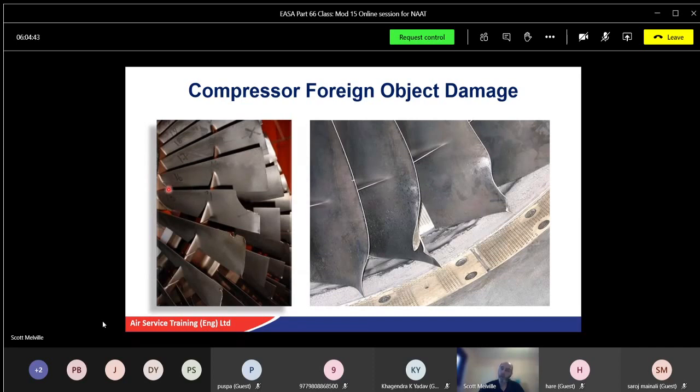Shouldn't really do that. That X there, that's a common practice of marking the top blade, okay, maybe as a reference point. If you're checking fan blades, check at the bottom, especially in the big engines on 747s or whatever, your big huge compressor. We'll bring the blade down to the bottom, start at the bottom and just move the compressor blades one at a time, looking up and down. That saves you looking at the top as well.